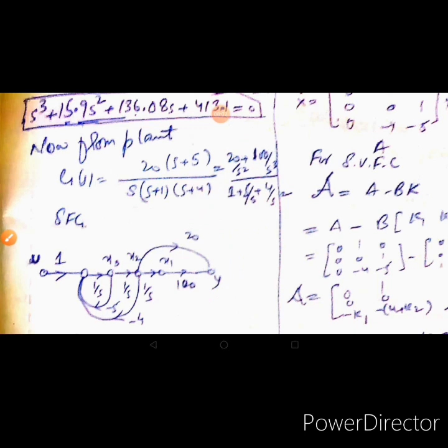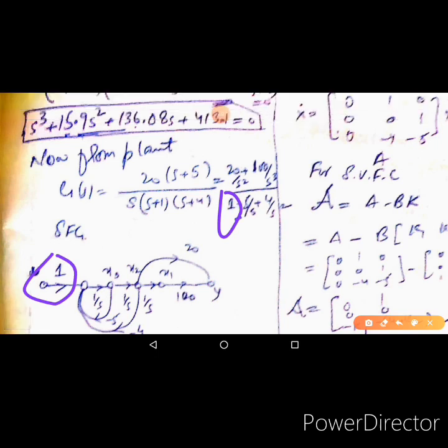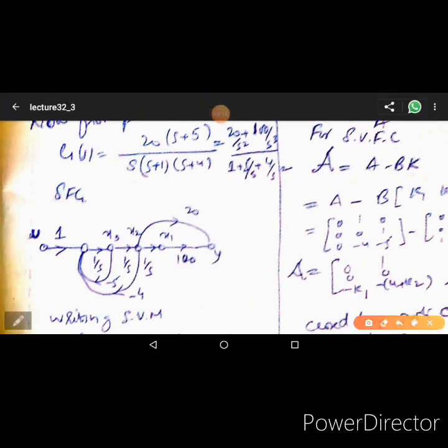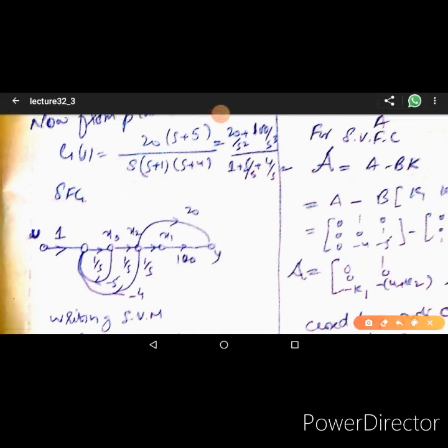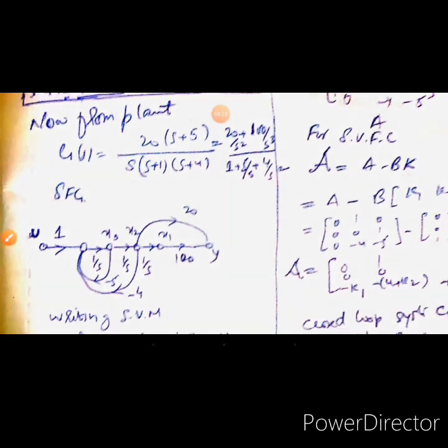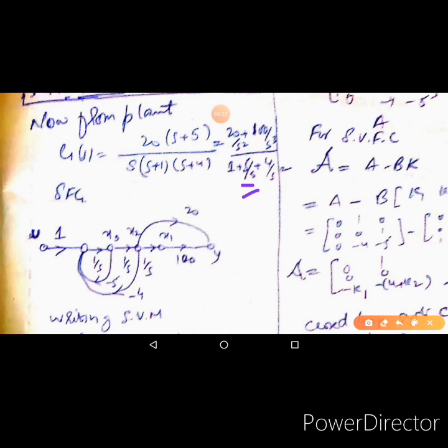This one corresponds to this input signal, and we have a plus sign over here, so we use negative feedback, like I had mentioned in the class as well. When we were having the conventional classes, the signal gets integrated once, it is multiplied with 5, and we have a negative feedback.